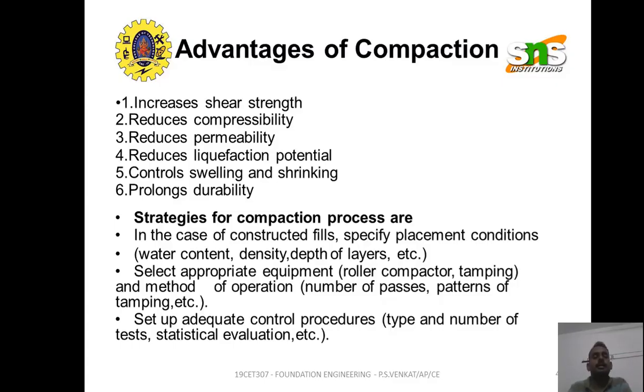Next thing is it controls swelling and shrinking of soil. When you consider a clay soil, on addition of water, there will be huge expansion, that is swelling of soil. On the other hand, where there is no moisture content present, the clay soil shrinks or decreases in volume to a greater extent.